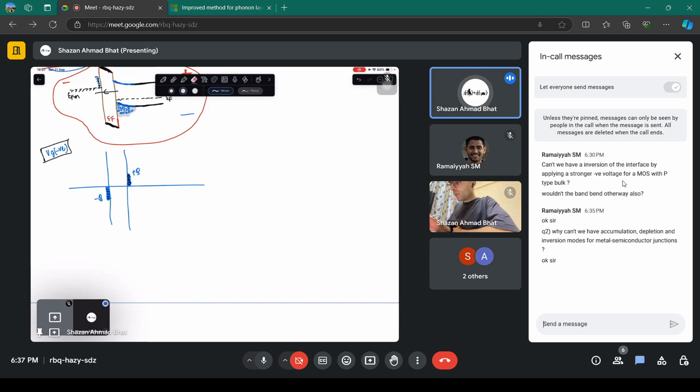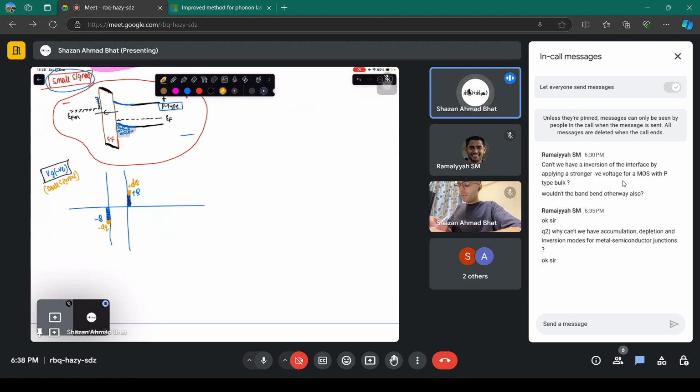So just follow the color coding because I'm going to use the same color in drawing the charges. Now, when you apply a small signal, it's very small. It's going to slightly increase the positive holes on the P side. This is plus delta Q charge, let's say dQ, and the same is going to appear here as minus dQ charge. On the metal, there are so many electron reservoirs that it doesn't matter much; there is only a slight increase in the negative charges. That is when VG is negative.